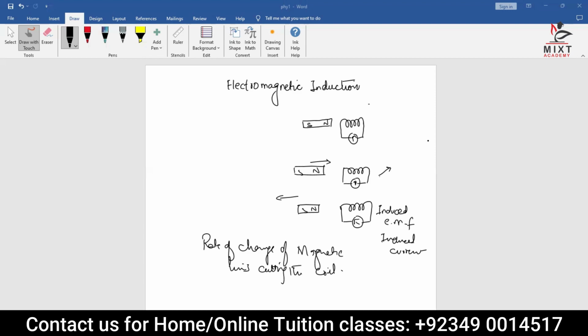Third case. Draw the diagram quickly. When a magnet is moving away from the coil, the ammeter shows deflection in the opposite direction. Reason: when the magnet is moving away from the coil, the rate of change of magnetic lines cutting the coil changes, meaning it reduces, which induces current in the coil.